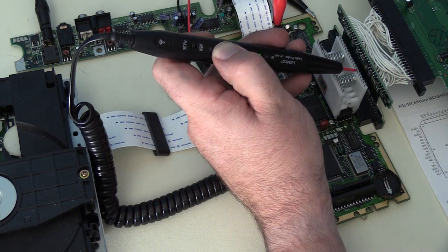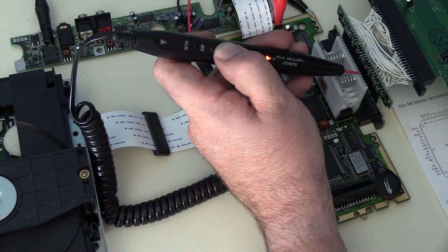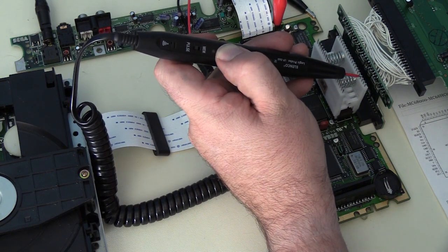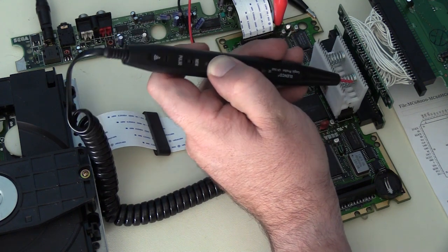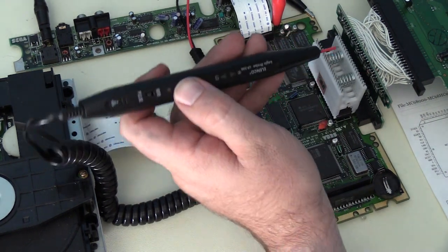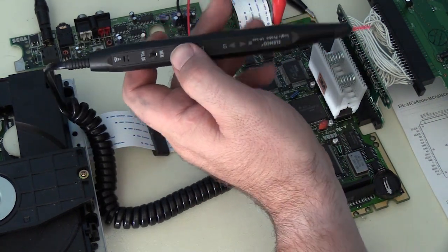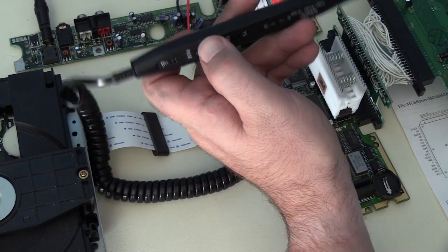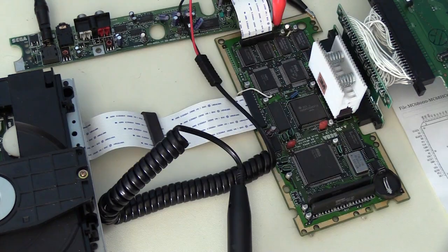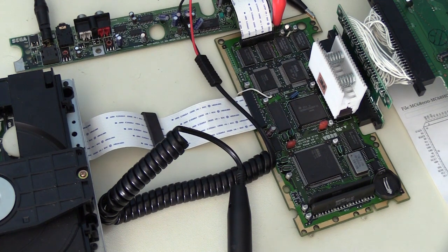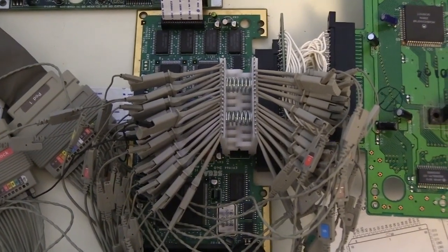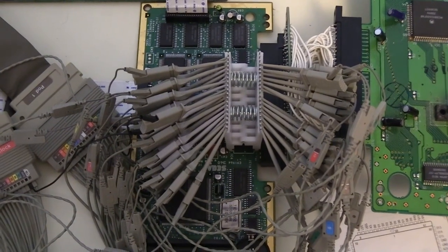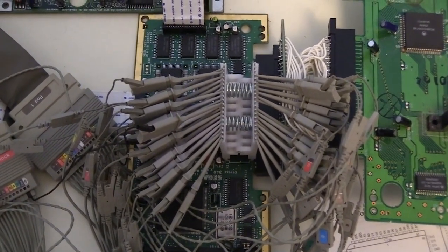But at least by checking every pin, we can make sure that there's no floating signals where there's not supposed to be. You can see I do get a reading off every pin, so every pin's connected, we don't have any floating lines, the chip's getting power, the chip's getting ground, there's just no activity. The logic probe isn't telling us much here except that every pin's connected, so that's when we had to move on to the logic analyzer. Okay, so here I've hooked up the test clip with probe leads for the logic analyzer.